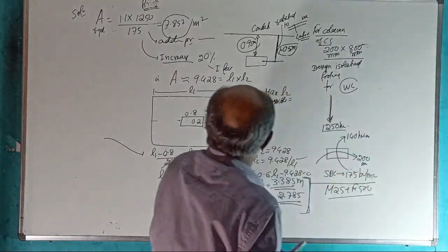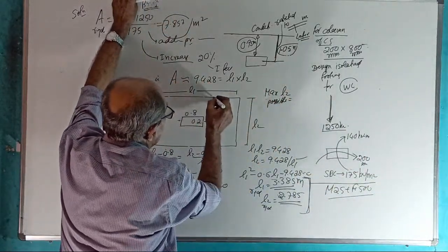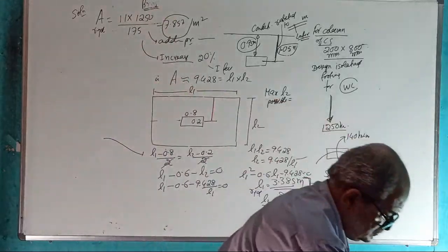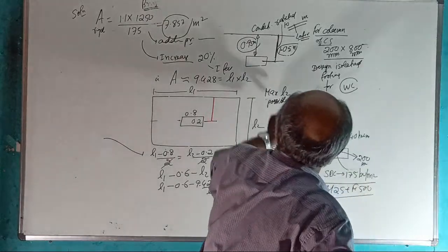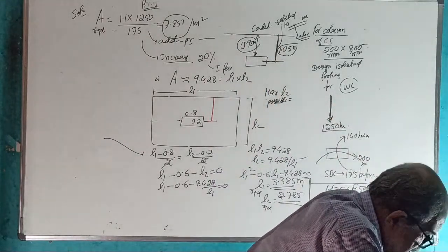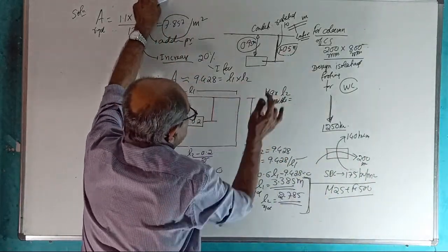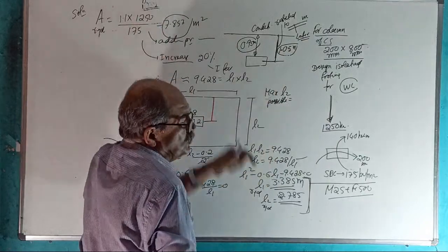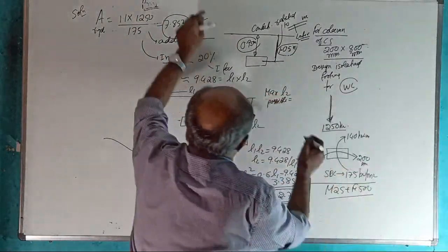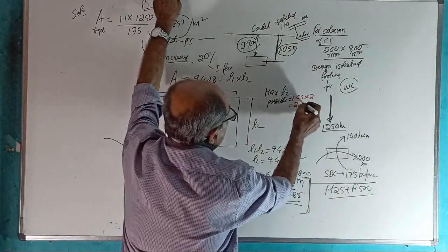Answer, tell me. Those who refer to 1.05, it is from the center of the column, this distance. So, what is the maximum L2 possible? If you refer to this 1.05, how much? If from the center of the column the restriction is 1.05, what is the maximum L2 possible? 2.1 meter. Why? 1.05 into 2 is 2.1.